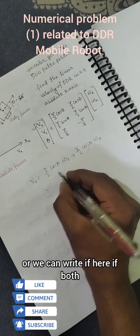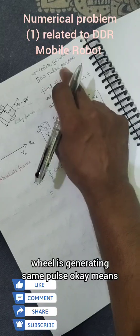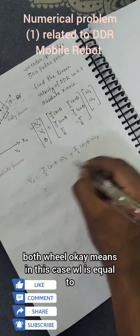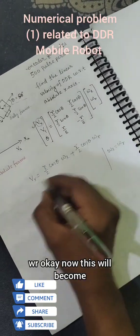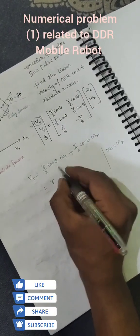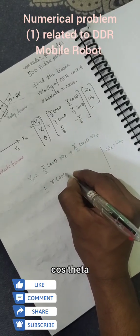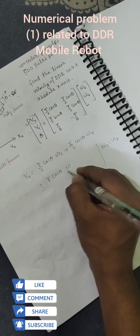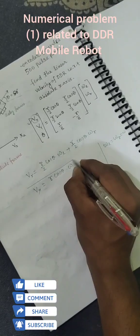Or we can write, if both wheels are generating the same pulse, meaning the angular velocity will be the same for both wheels, that is WL is equal to WR, then this will become Vx equal to r cos theta into W.